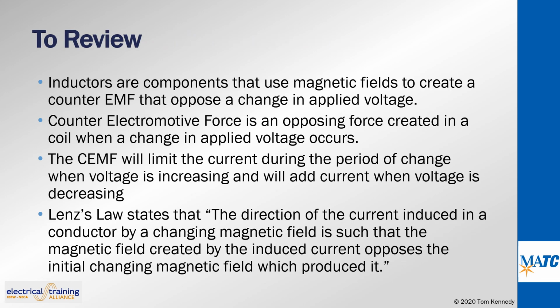To review, inductors are components that use magnetic fields to create a counter EMF that opposes a change in applied voltage. Counter-electromotive force is an opposing force created in a coil when a change in the applied voltage occurs. The CEMF will limit the current during the period of change when voltage is increasing and will add current when voltage is decreasing. Lenz's law states that the direction of the current induced in a conductor by a changing magnetic field is such that the magnetic field created by the induced current opposes the initial changing magnetic field which produced it.